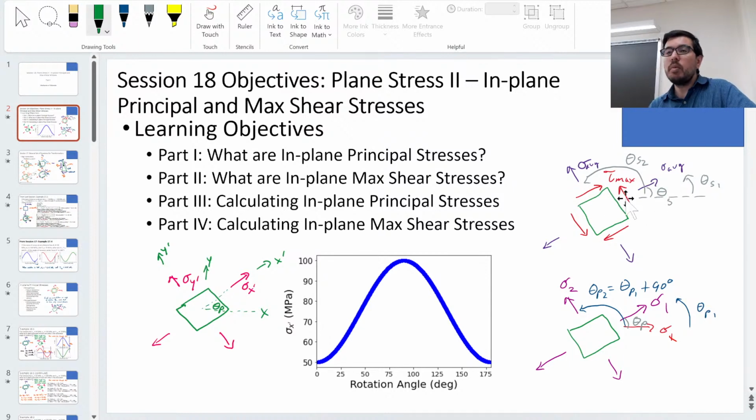Do you remember when we talked about torsion problems and we're like, hey, there's no normal stress on this element? We've now seen that for the combined loadings. We just look at what that torque is doing and there's no normal stress on those elements. So that's pure shear. That pure shear situation, tau max, corresponds to that calculated Tc over J that we've had.